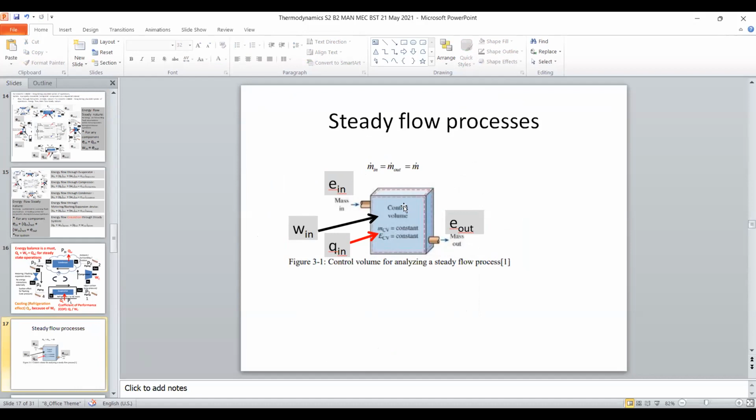Now, let's say this can be evaporator, condenser, compressor, flashing device, whatever. So here, the inside working fluid. So this energy in plus W in plus Q in, the energy being received. Okay. Let's say it's W in, Q in, E out, E in. Okay. Good. Then you can write the energy balance.